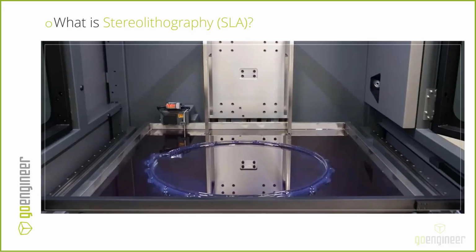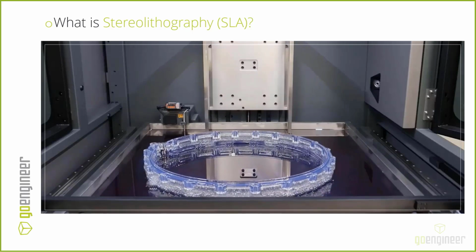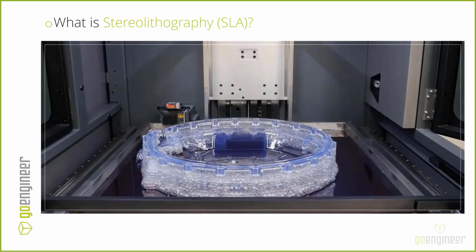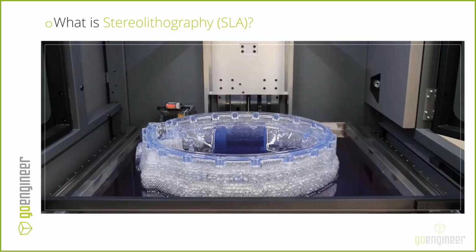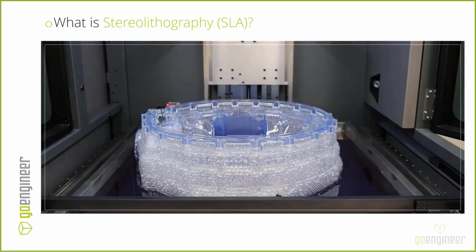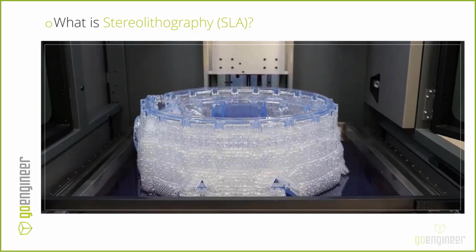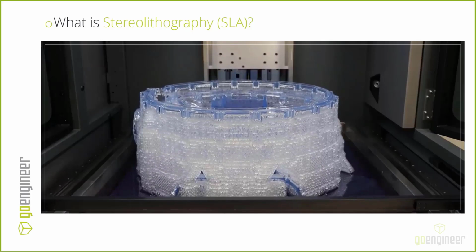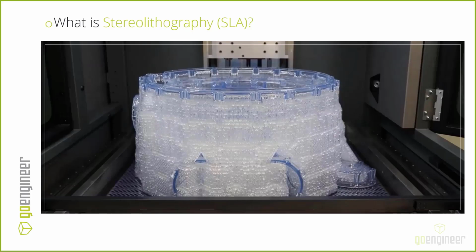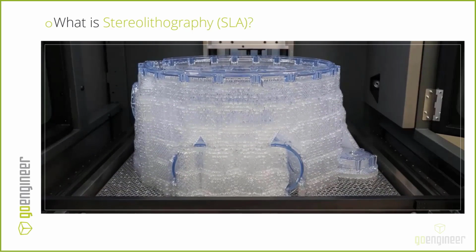Exposure to the UV laser light solidifies the cross-section and adheres it to the layer below. After one complete layer has been scanned, the platform descends by a single layer thickness, typically around 4 thousandths. Then a resin-filled blade, which is called a recoater, and you'll see this as a common theme across a few of the different AM technologies, moves across the vat, applying another layer of resin on top of the parts. On this new liquid surface, the next layer is scanned, adhering to the previous layer. The process continues until all layers of all parts have been scanned. After building, parts are raised from the vat and drained, and then they are cleaned in a cleaning solution and finally cured in a UV oven.